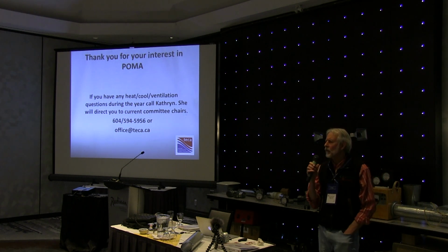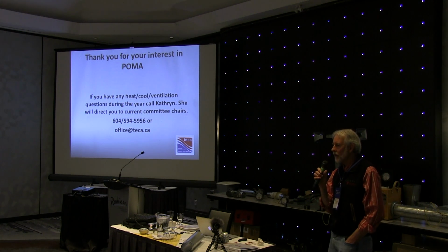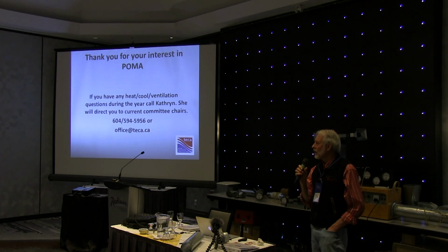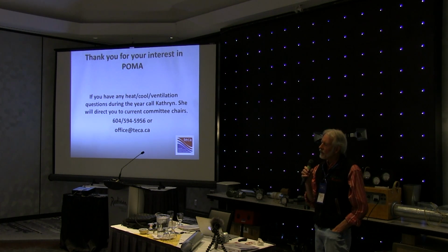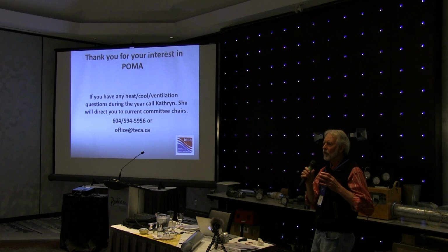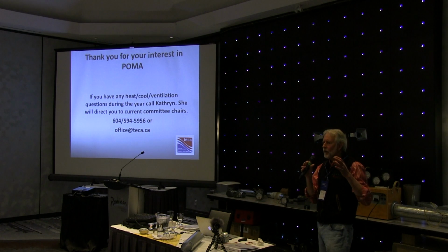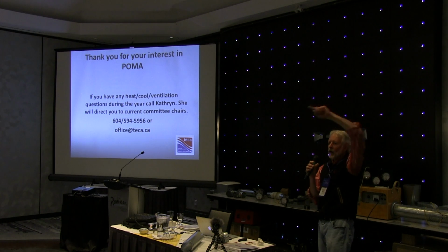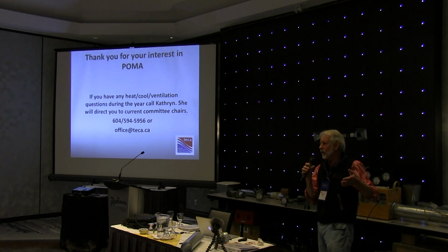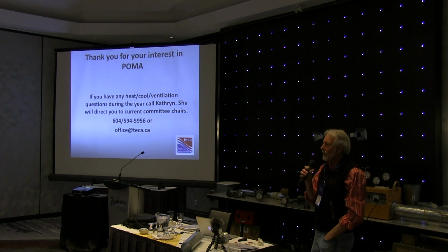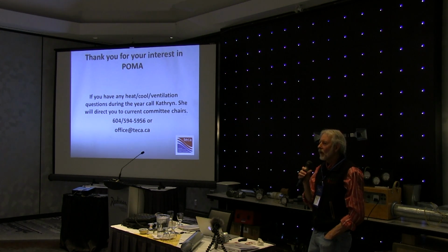I'm going to dodge your question from the point of view of code, but deal with it practically. The question that comes up, what do I think about using a joist space for cold air return? What I'm seeing happening right now is, in simple form, we should look at houses as more or less non-compartmentalized. We're building a better enclosure. The interior partitions leak like hell because we don't really care about sealing. So we basically have a non-compartmentalized enclosure, albeit with doors, they still have a half-inch undercut. In my opinion, what I've learned in the last 40 years is the point of return is far, far, far less critical than ample return.